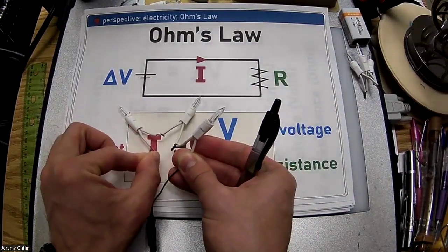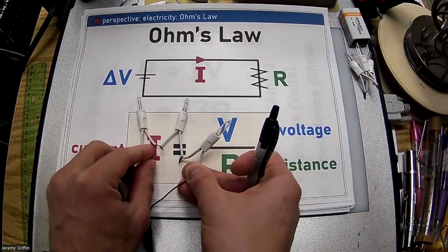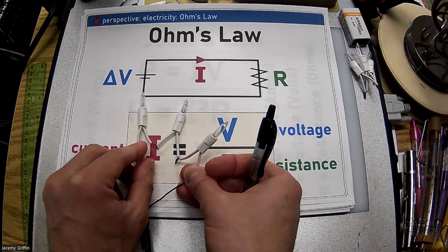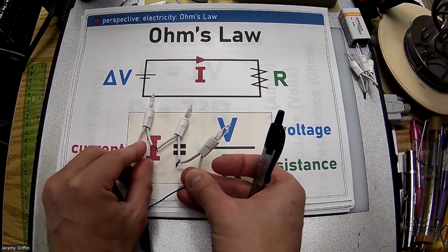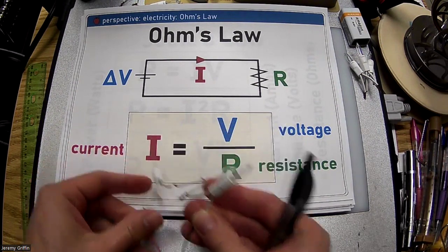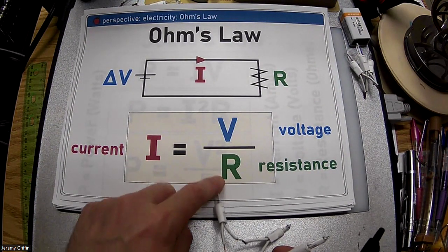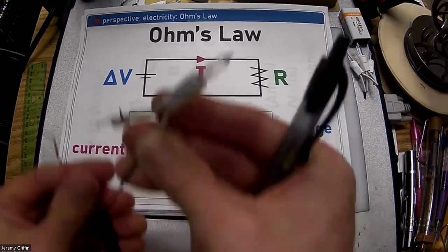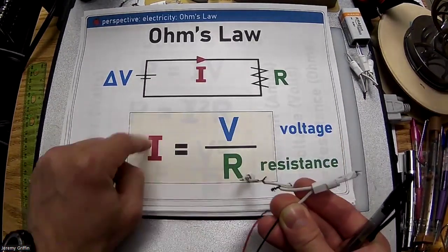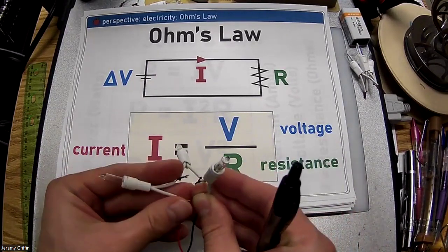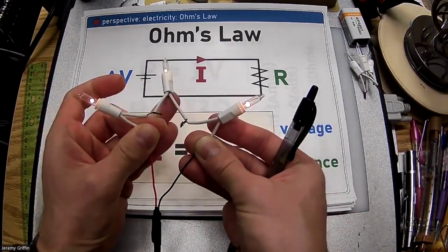But if I move this lead over so it gets all 3 bulbs in, that's effectively tripling their resistance. See how they're all 3 in a row? It's called in series. So 3 in a row, triple the resistance. If I triple the resistance, notice it's the same voltage. I've still got the same potential difference of 5 volts across these leads. But I just tripled the resistance, so I get 1/3 of the current, and then them being dim.